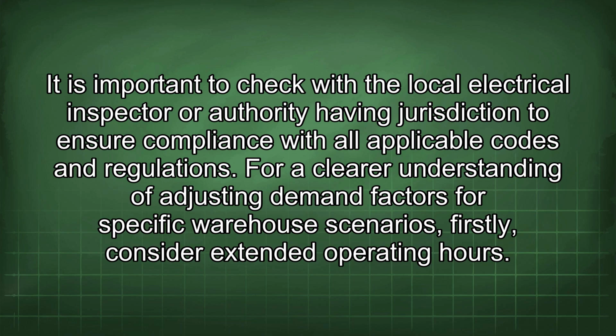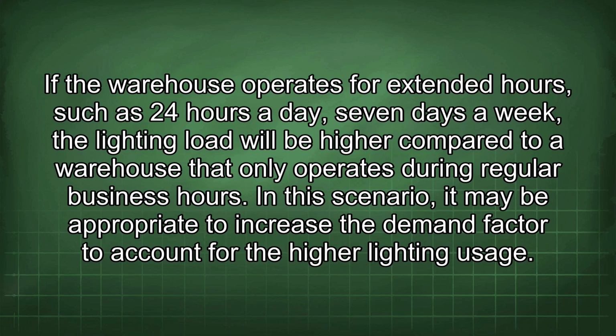For a clearer understanding of adjusting demand factors for specific warehouse scenarios, firstly consider extended operating hours. If the warehouse operates for extended hours, such as 24 hours a day, 7 days a week, the lighting load will be higher compared to a warehouse that only operates during regular business hours. In this scenario, it may be appropriate to increase the demand factor to account for the higher lighting usage.